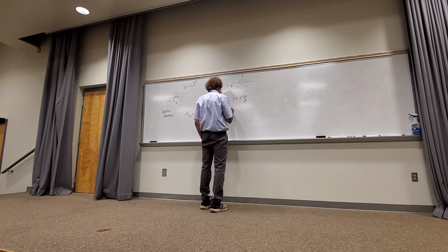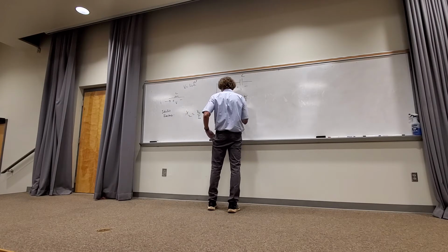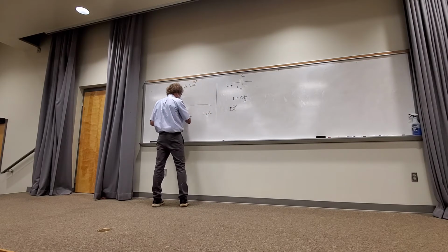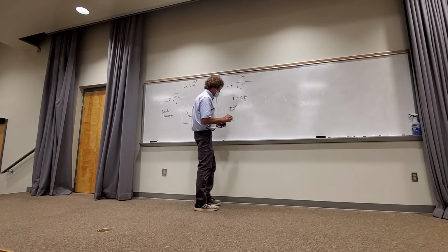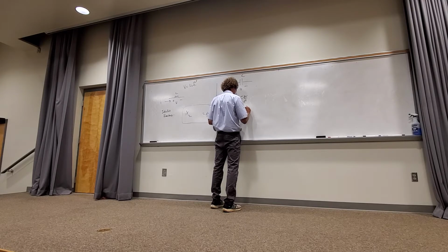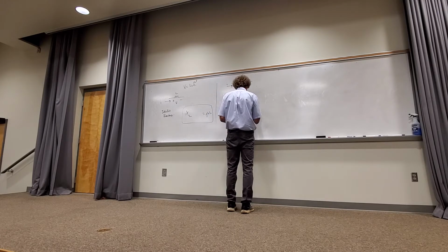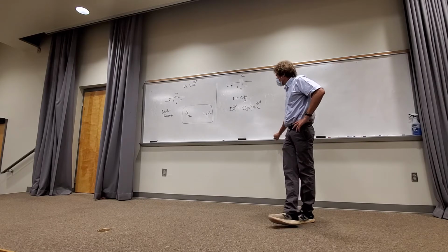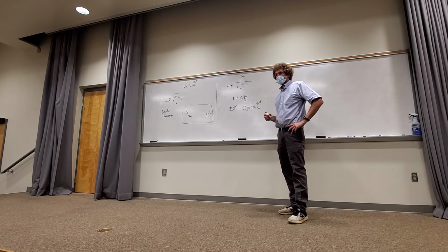And we find here that I naught e to the j omega t, and actually, why don't you just call this X sub L? Don't even put that in here. Call this the inductive reactance, is equal to C times j omega times V naught times e to the j omega t. Here the derivative was on the voltage, not the current, so there's a j omega that pops out there. Y'all see this, class? It won't be that bad. How many see this right here?